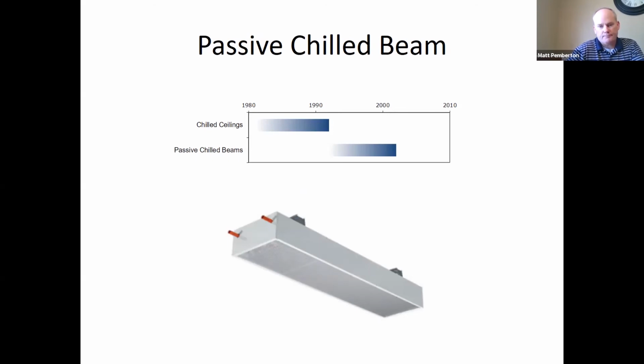And so when we're doing cooling only, the radiant effect is kind of mitigated or reduced by the fact that there's a coil and then there's a gap and then there is this perforated panel. So there is a tiny, tiny bit, and in the selection software program that is accounted for, but it's large majority, not necessarily 95+%, but it's all pretty much convection on the cooling side of things.